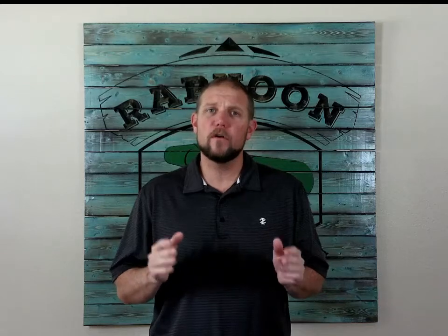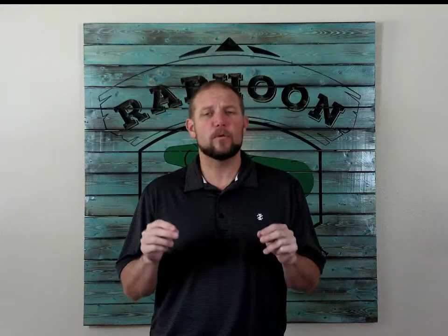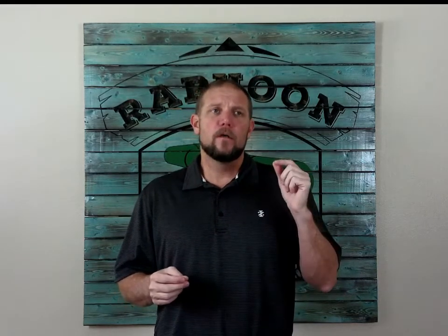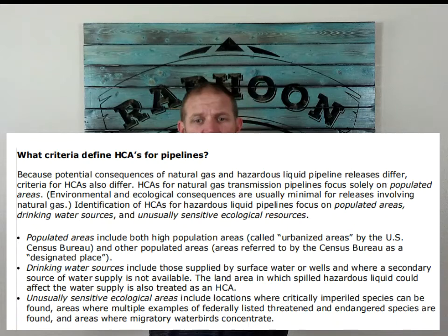So, given all of those areas where HDD is used, I want to explain to you why I focus so heavily on the importance of doing an HDD and protecting it right when you build it. The definition of a high consequence area from PHMSA is an area that includes populated areas, drinking water sources, and unusually sensitive ecological resources.